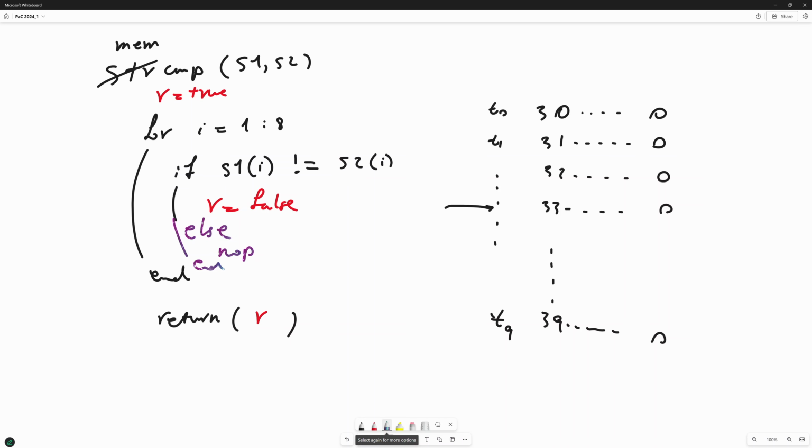You don't know, because it's just a high-level program. You have to look at the assembly, and you have to look at the number of clock cycles every instruction takes. Only in that case, only if you look at the assembly code and the machine code of the microcontroller, will you be able to say if this implementation is fixed time or not. Because fixed time implementation is super important, not for this strcomp or memcomp, it's for entire cryptographic primitives.